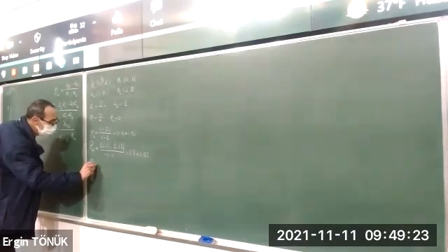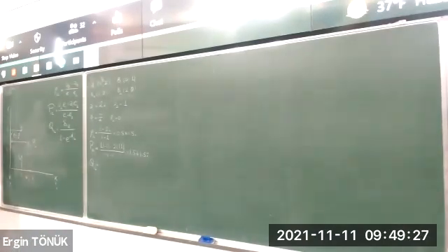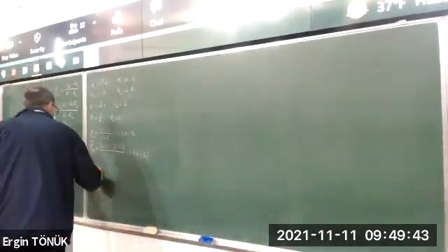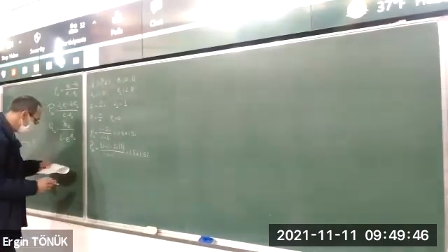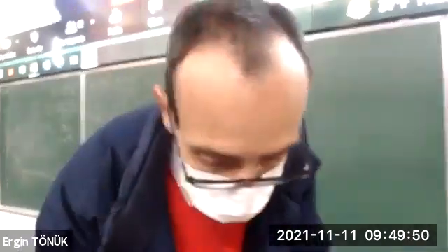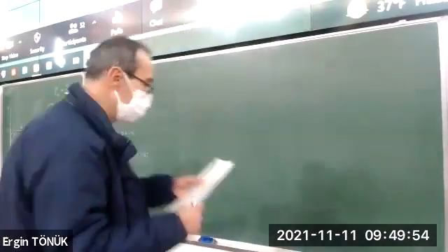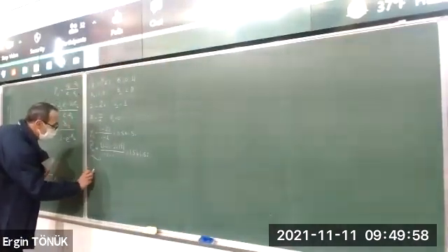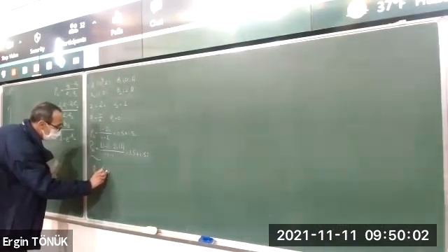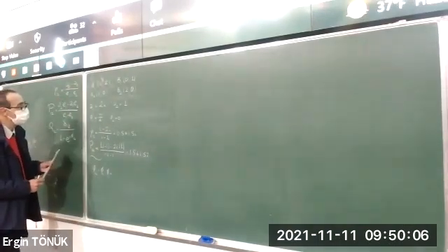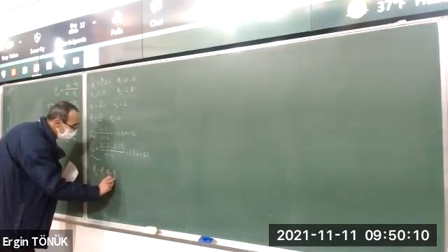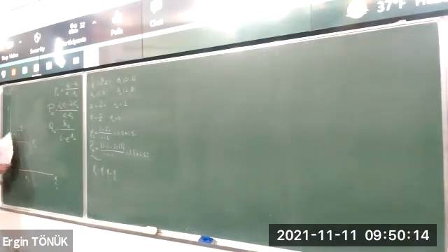Now we can use the relative method as well, which is Q12. This time Q12 is the vector with respect to the fixed coordinates, if you like, that points from A to the pole. Okay. So actually, I should do prior computations. Let me do that first, not rush to this. So phi1,2 is phi2 minus phi1, which is 0 minus pi over 2, which turns out to be minus pi over 2. So is it the case? Yes, it's rotating 90 degrees clockwise.